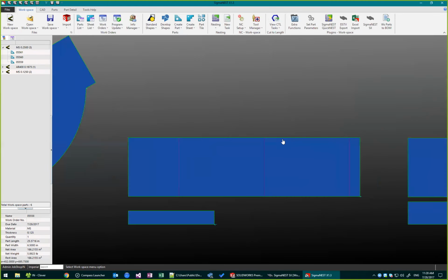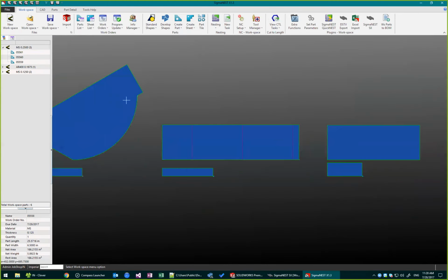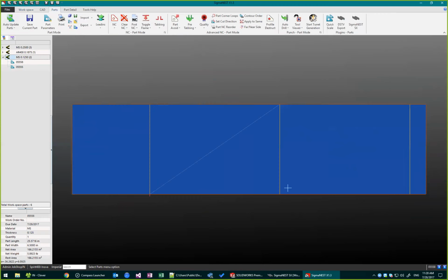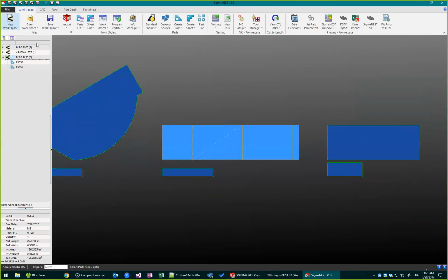Additionally, the bend lines were brought over. There's options here in our configuration to mark those or keep them as detail notes where they're not cut. They just might show up on the reports. They're great for maybe dimensioning. I can throw in a dimension saying this bend line is here, and so on.